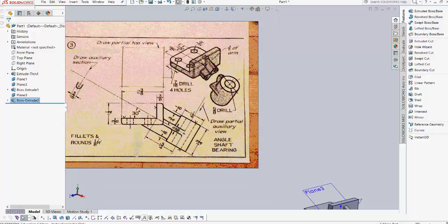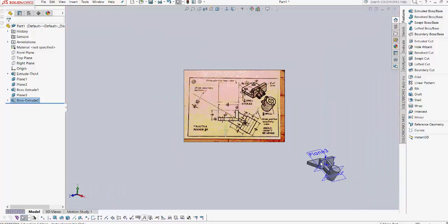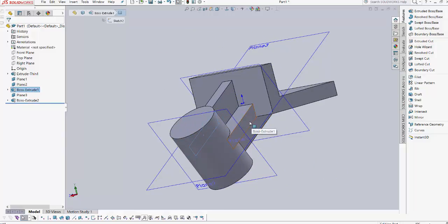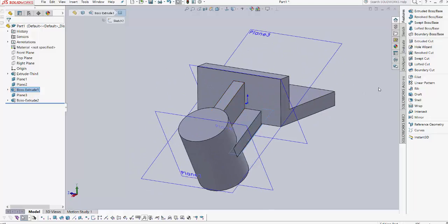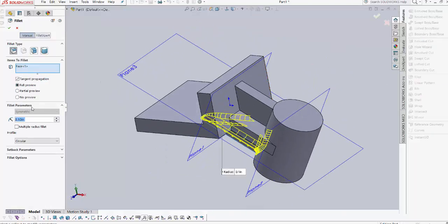Most of these fillets and rounds are 1/8. The exception to that is the cross itself. You'll notice they're 5/16. They're a full half round. That's why there's a center mark in there. And so that means when we come back over here to do this, this area and this area and the other two, this one and this one, all are a full half round with a 5/16 radius. So the way we do that is we go to fillet.